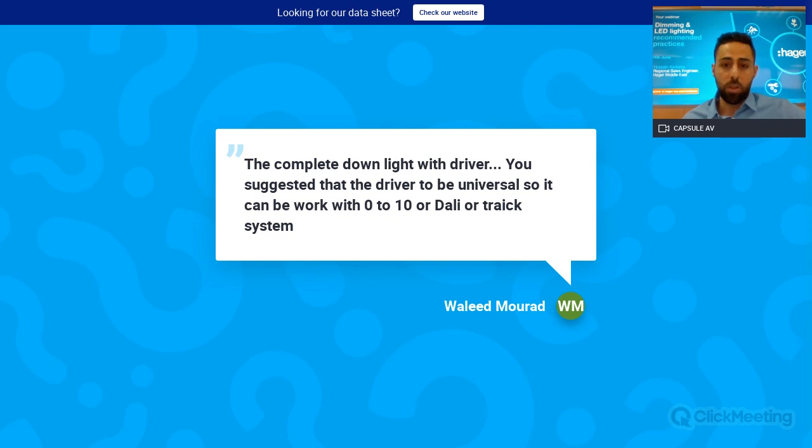It can come with either 0 to 10 or DALI, but it comes with a relatively higher price than others. So phase dimming is separate, and for 0 to 10 or DALI, yes, you can have one driver with 0 to 10 or DALI. Ask your lighting supplier; he will assist you on that, and he will give you options.